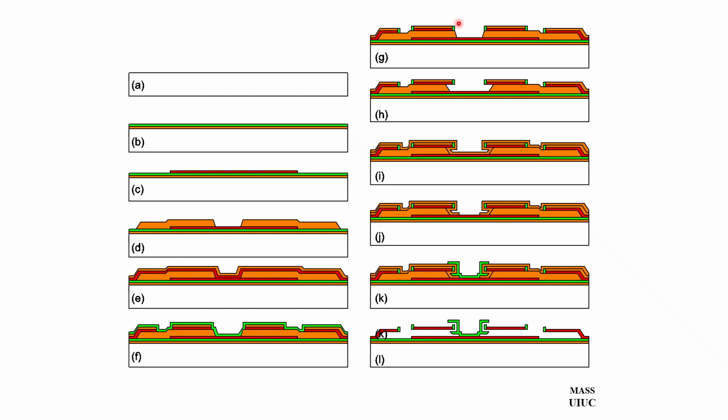So this way you can leave some silicon nitride on the vertical surfaces, but remove all the silicon nitride on the frontal surfaces. And after this, you can do a timed isotropic etching to create desired undercut. The undercut creates a spacing.